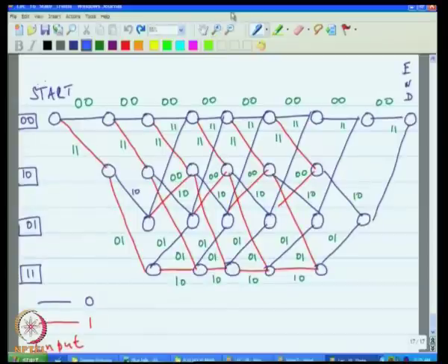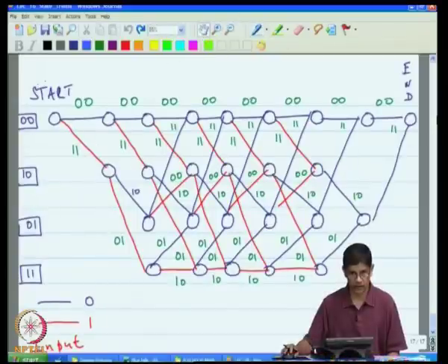So, here you have the trellis. When we looked at the Viterbi decoding algorithm, we saw that the algorithm only moves from left to right. So, you may be a little bit puzzled, how come you have a forward and backward? Well, the reason is that in the Viterbi algorithm, at every recursion, we compute metrics assigned to the nodes at a certain node level, and we move from node level to the next node level, okay? And we keep going from left to the right.